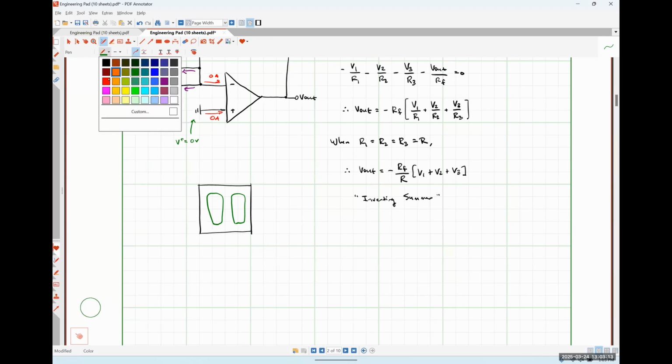And so there is a load cell connected here, here, here, and here. So each of these load cells converts effectively how much pressure I'm putting on them because of how much I weigh into an electrical signal. So it takes in force or pressure and it outputs a voltage. Well, then an op amp is actually used to add all of those voltages together, and that will give me an indication of what my weight is, okay?